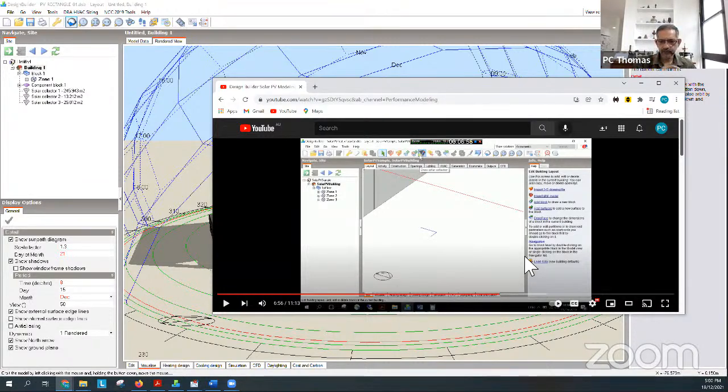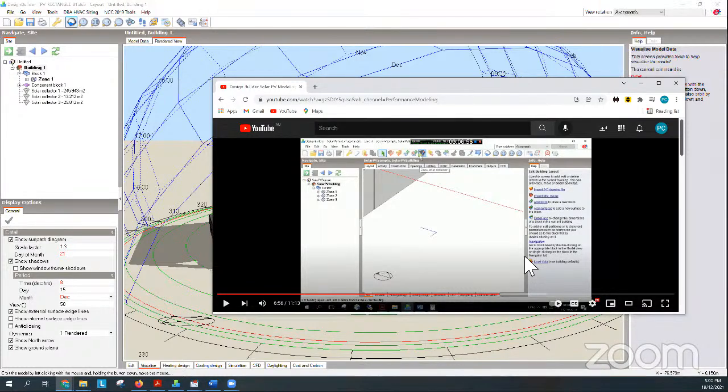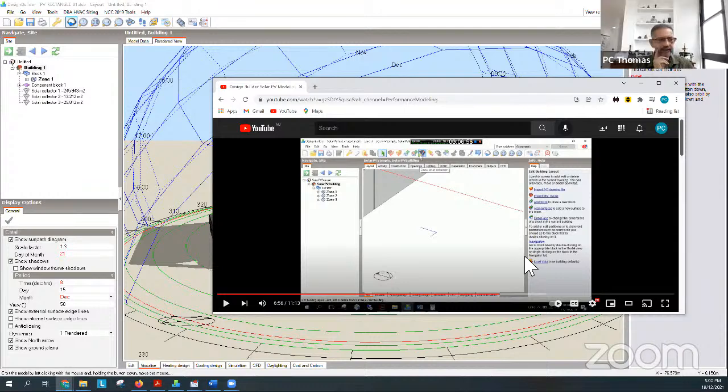Also, the output from the solar PV system, you can look at it on the hourly outputs. So you can see every hour how the outputs are varying. And I would suggest you pick a couple of hours that you know the array is shaded, and then you look at the output before it's shaded and after it's shaded, and it should really be able to show you what's happening there. That's what the model's designed to do anyway.